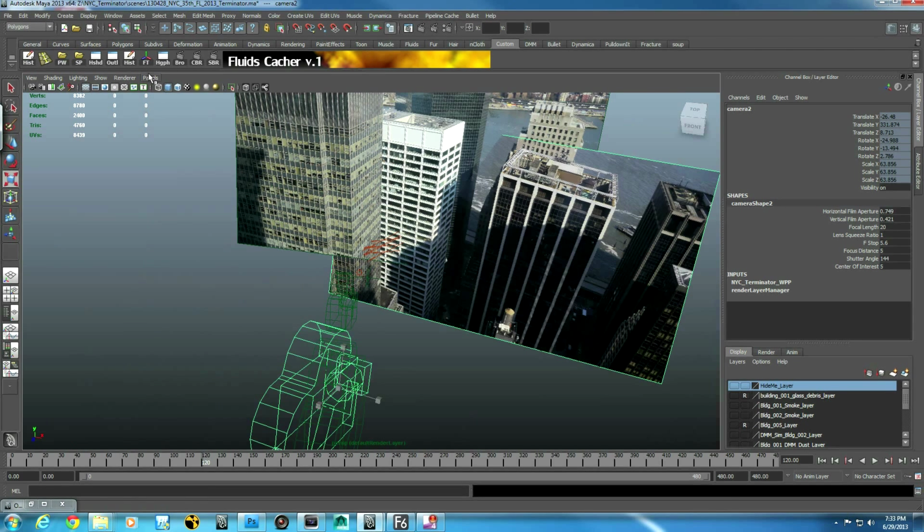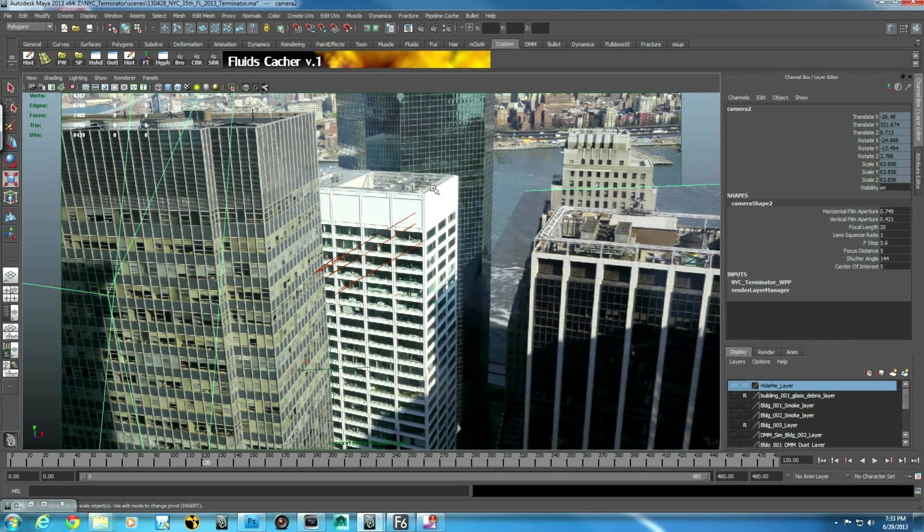What you need to do is look through any one of the two cameras. So let's look at camera 1, and when you look through this camera, you see that the building is cut off here, because this is the end of the image plane for camera 2. That's the one that we have selected. We are viewing through one, and that building is continuing up in image 1. So I had to fine-tune these values here for camera 2 until both image planes showed that the building continues. It didn't really take that long, maybe 10 minutes max, and I was done.